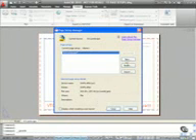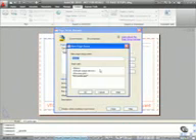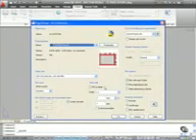Let's go to New, and we're going to create a new page setup name, which is A3, like that, and we're going to put a dash there, and it's going to be a DWF, and then plot, like so. Make sure you get that spelt correctly, avoid that capital L, like that, and then I'm going to OK that.